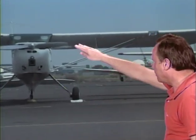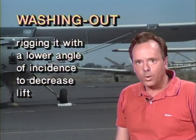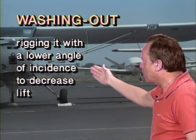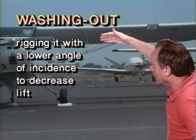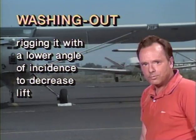and we're talking about the angle of incidence of the wing all the way from the root to the wing tip. Washing out of a wing is done by rigging it with a lower angle of incidence to decrease lift. So if you change the angle of incidence of this wing so that you lower the angle of incidence to decrease lift, that's called washing out of the wing.